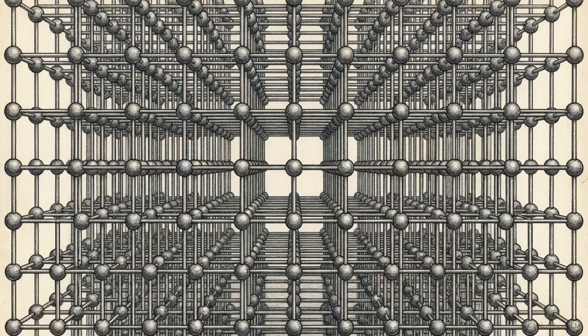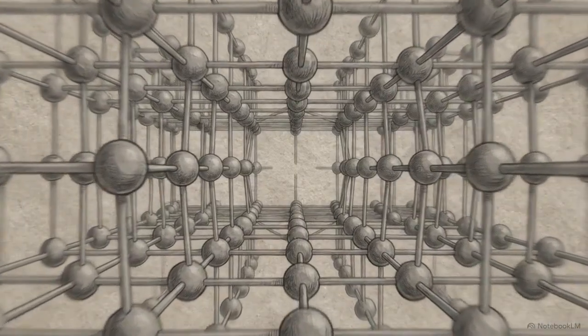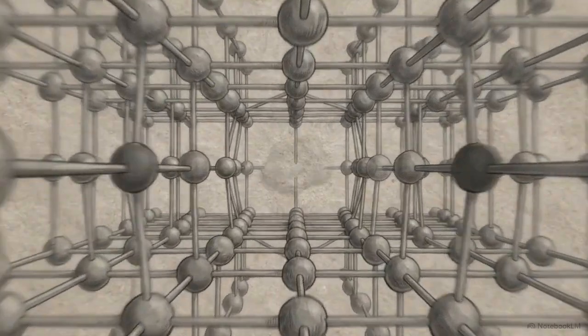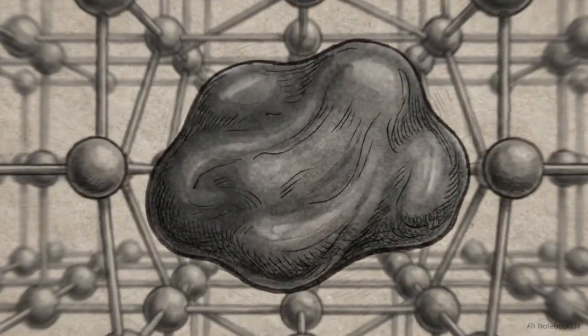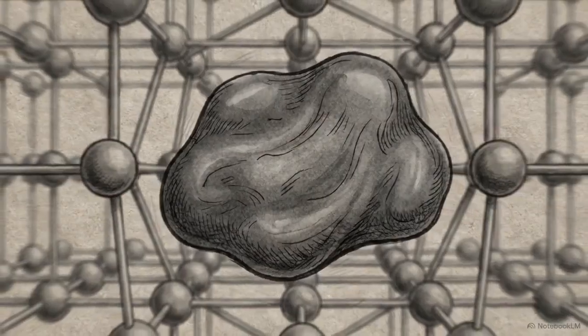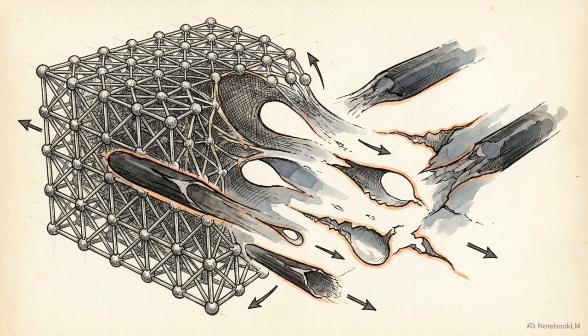Iron itself does not behave this way. This severe mechanical anisotropy is a structural defect engineered into the plate by processing artifacts known as non-metallic inclusions. To understand this failure, we must look inside the steel matrix at a microscopic scale. Scattered throughout the iron lattice are discontinuities, pockets of foreign chemistry. When the steel plate is placed under extreme tension, it rarely snaps cleanly. The primary mechanism of failure is a physical process called microvoid coalescence.